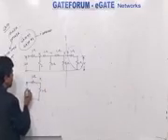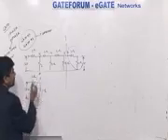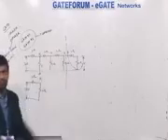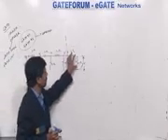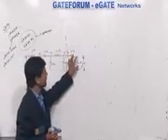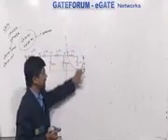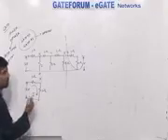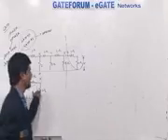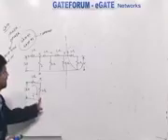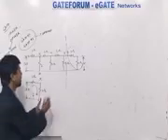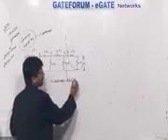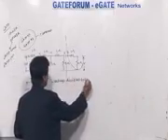Now this is 16 volts. This is the equivalent circuitry, because the series arm resistors are the same and the shunt arm resistors are the same. This 1 ohm is the contribution in the series arm, and 1 ohm plus 1 ohm is present in the shunt arm across this Z branch. Now I know the basic law: voltage is divided, because the equivalent circuit is nothing but a series circuit. So the voltage division rule is applicable, and by using it I can find the voltage Vx.